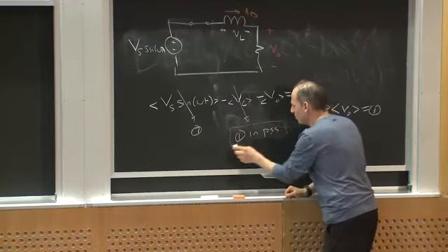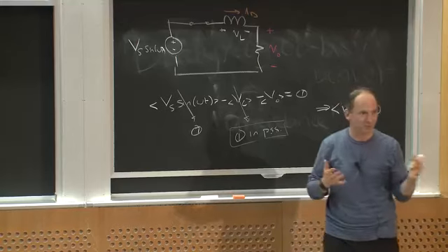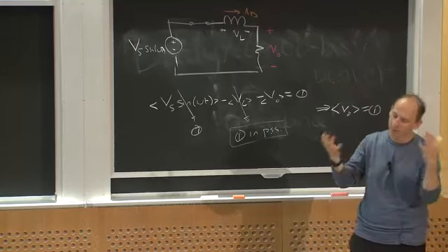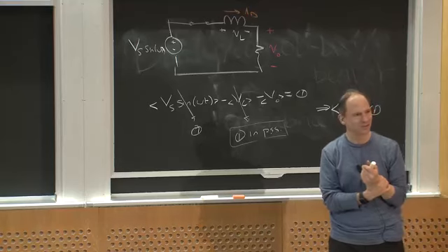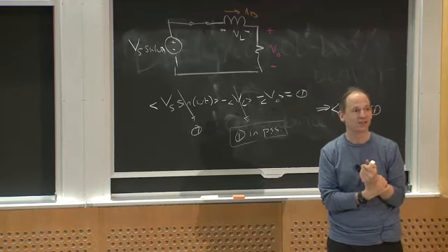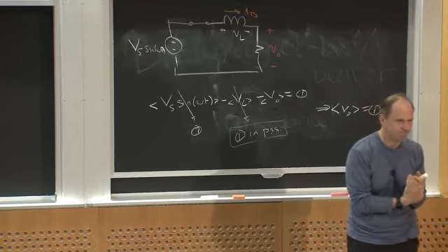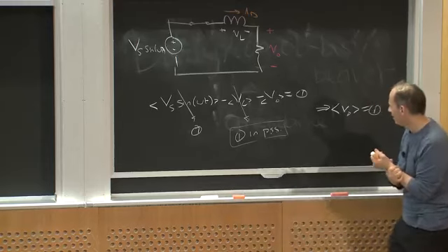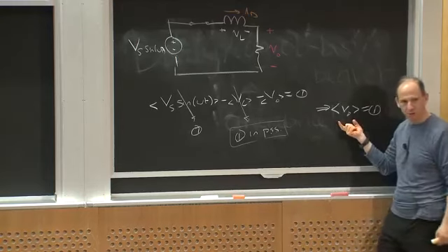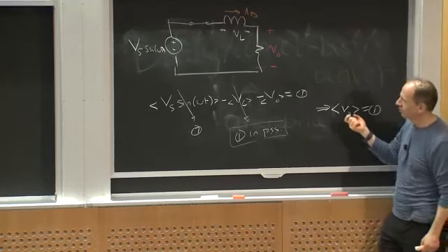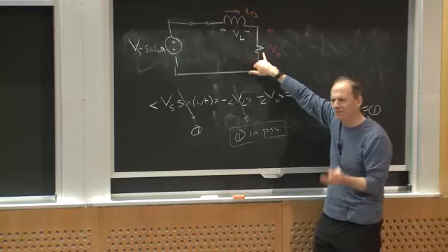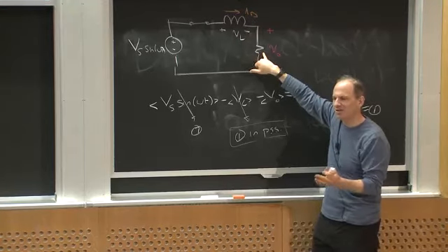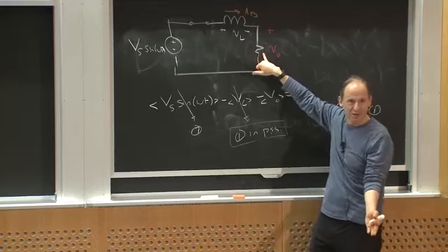But what this voltage being 0 in periodic steady state told me is I've made a mistake. I've done something, perhaps not stupid, but I've gotten over aggressive with my assumption that this diode stays on all the time. And in fact, I can tell that because if the average voltage was 0, and presumably some of the time this current's positive, so I have a positive voltage, and if its average is going to be 0, then some of the voltage must be negative some of the time.